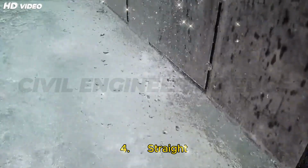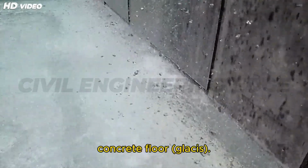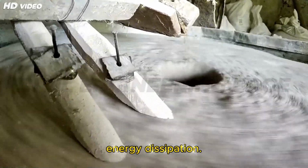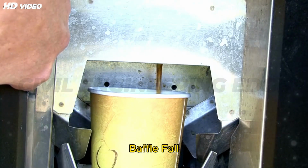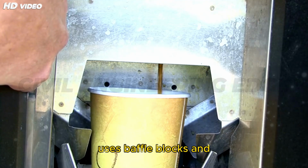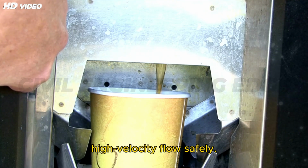4. Straight Glacis fall. Features a sloped concrete floor glacis. The hydraulic jump forms on the stilling basin for energy dissipation. Suited for moderate to high discharges. 5. Inglis or Baffle fall. Designed for high discharges. This fall uses baffle blocks and a glacis to control high-velocity flow safely.